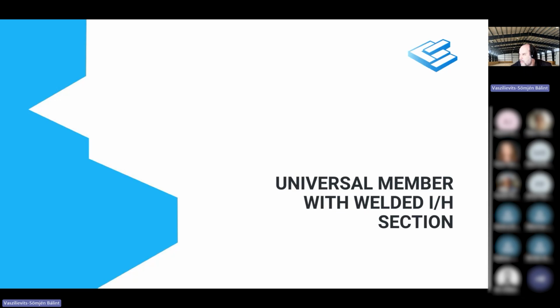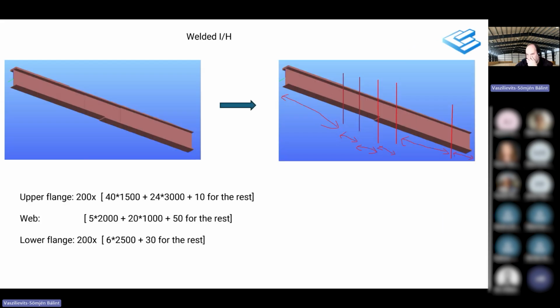Of course, with hot rolled sections, the options are much more limited. What I can change is just use a completely different profile after a certain level. For that I have shown an example. The new eccentricity nicely solves it. There is no other need to better support that activity, or we can also add haunches. This has almost always existed in Consteel. So I think the modeling of hot rolled sections is nicely solved with the eccentricity, but if we want to model welded sections, then up to now there were a lot of difficulties with Consteel.